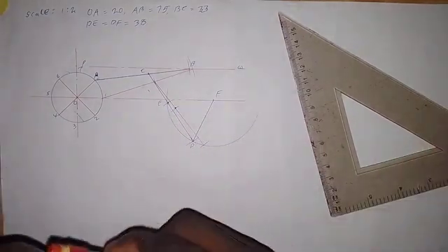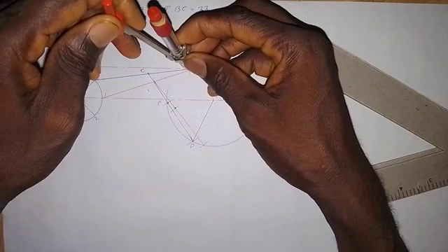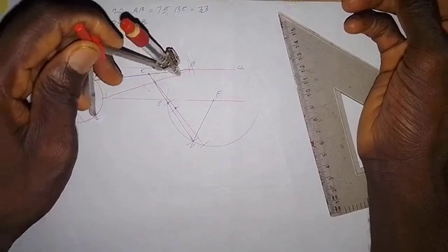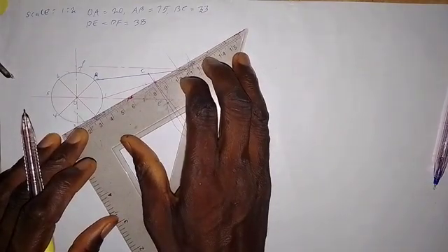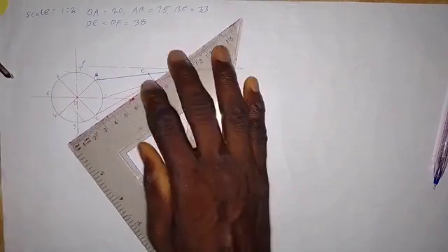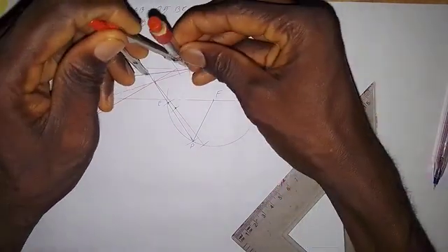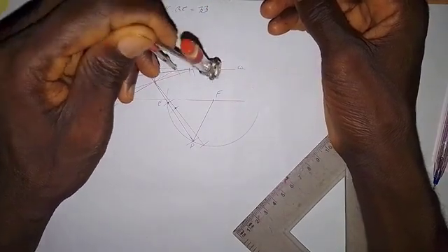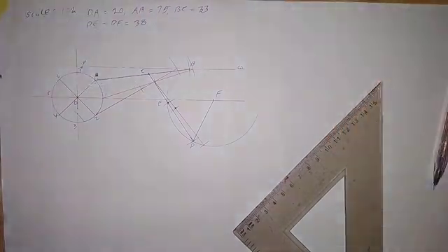So the next thing that I'm going to do is that I will take this 75 again, or AB. So I'll take this AB, then I'll put at point 2. Then I will make an arc on this line. So then I'm going to join point 2 and this point on line PQ together like this. Okay, so then we need to locate the new point C. So to do that, we take distance BC like this. Okay, so then we put the point at this new point B. So make an arc on this line. Okay, so this is the new point C.